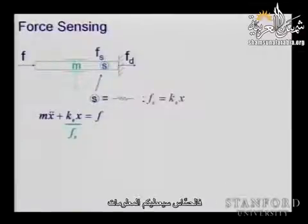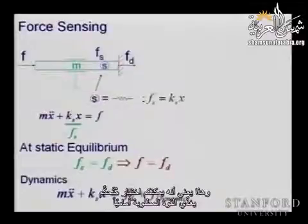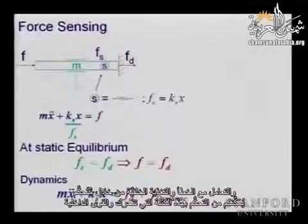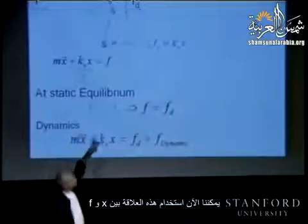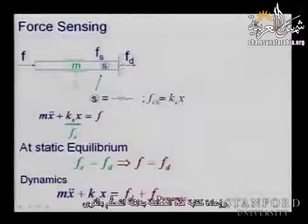So your sensor will give you the information, and now you can see that what you want is to achieve F equal F desired, which means that you can select a controller that feeds forward the desired force and deals with the error and the feedback through a controller that allows you to control this mass that is moving, but in terms of forces. Now, we can then use this relation between x and F and rewrite this equation in terms of force control.